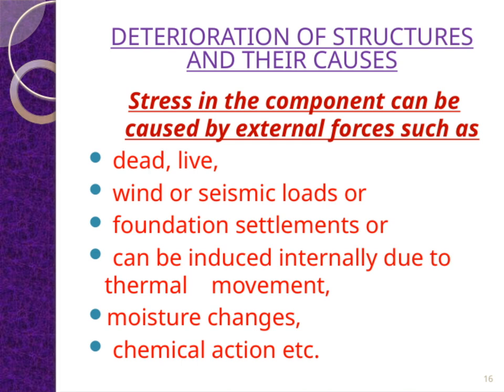On the other hand, stress can also be induced internally within the structure due to factors like thermal movement, where temperature changes cause materials to expand or contract, or moisture changes that affect material properties. Chemical actions, such as corrosion or other reactions, can weaken materials and lead to internal stresses. Understanding these causes is crucial because they directly impact the deterioration of structures over time.